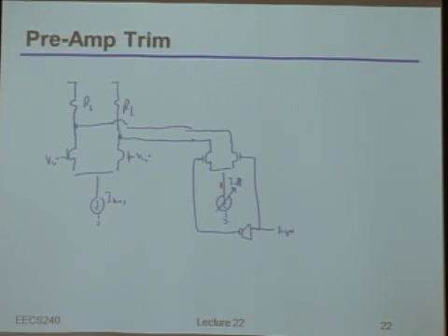As Paul was mentioning, one thing that's immediately nice about this is that I have to build this DAC here that has a lot of bits, or many unit cells inside of it. But if I keep this transistor here in saturation, meaning whichever one of these two is actually on, it acts like a buffer. It acts like an isolation. Because remember, we said that there's always a gm ro relationship between the voltage swing happening here versus the voltage swing happening there.